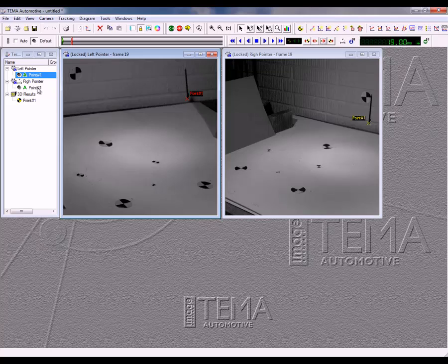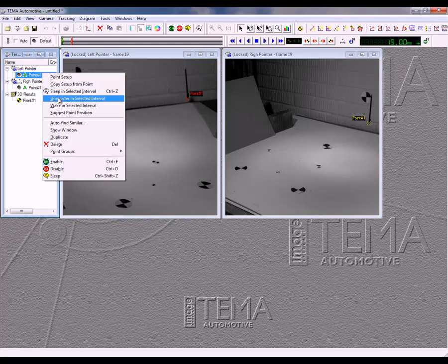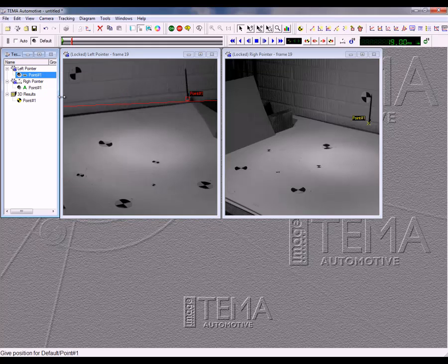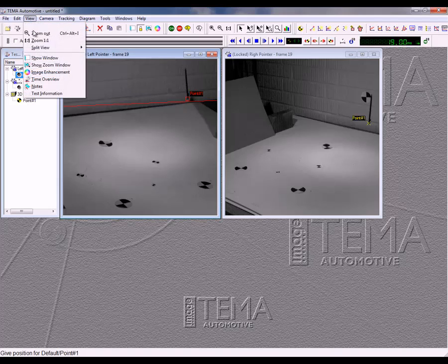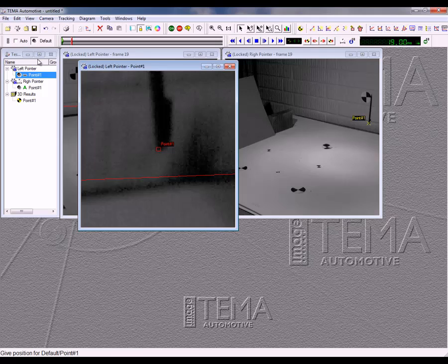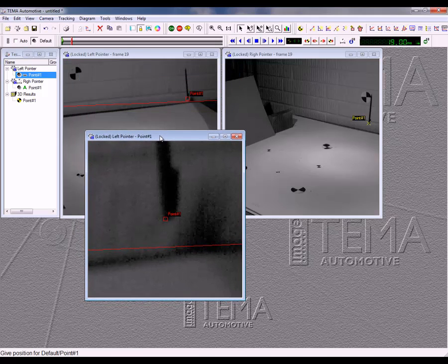There is a back projection feature which is very useful. Here a point has been unregistered in one image, and the back projection line now showing is the line on which the program expects the point, tracked in one image, to fall in the other image. This can help in the location of a feature you're trying to track, and also gives a good idea of the accuracy of the 3D tracking.